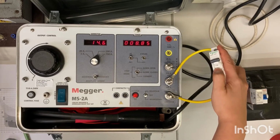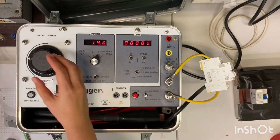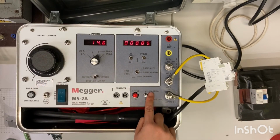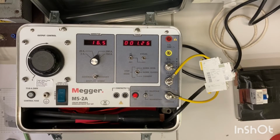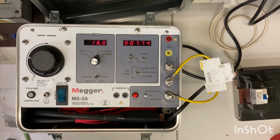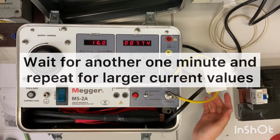So we need to cool down the MCB once again and repeat the procedures for other larger currents. For a current of 16 amp, the disconnection time is 7.74 seconds.